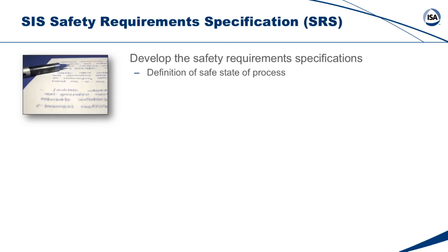This system has to bring the equipment or the process to a safe state. You don't really think the vendor or the system integrator knows what the safe state of your process is, so you need to document that. Also document any potential common cause problems, like plugging or severe corrosive service. If it's plugging service and high temperature, you don't want 10-meter long impulse lines of 1/4-inch tubing. They're going to plug on the first day. You need to specify all the materials of construction to make sure things don't corrode and fail within the first month. Common cause: a single stressor or failure that wipes out multiple things.